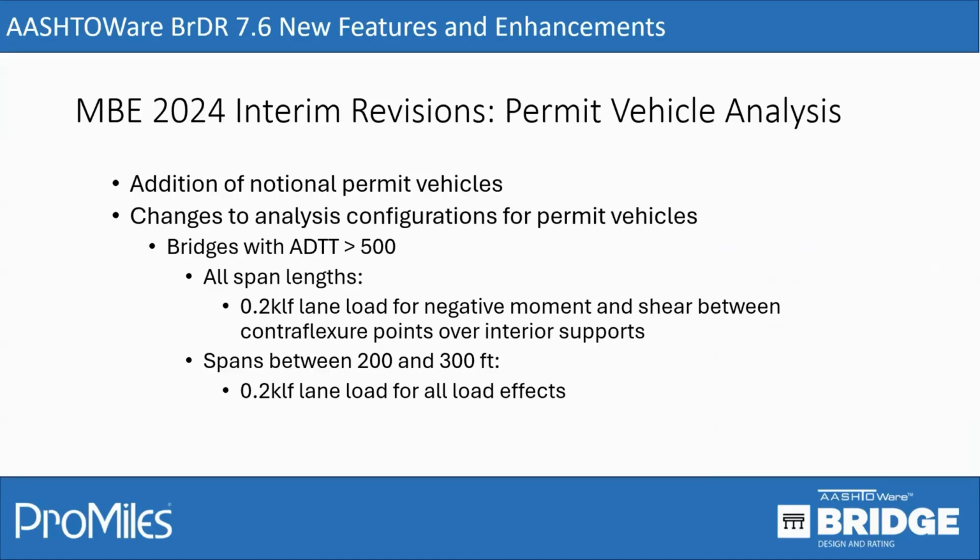So one of the two main things from the 2024 interim revisions is some changes to permit vehicle analysis. So this interim revision adds notional permit vehicles for analysis. Prior to that, it was just the actual permit vehicle. So notional vehicles are added to the specifications now and are supported in the software as of version 7.6.